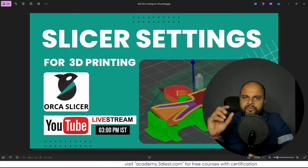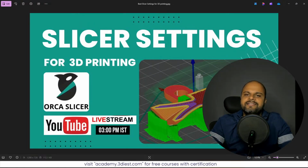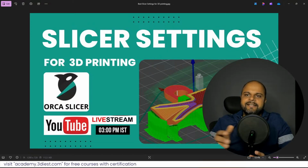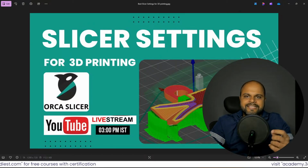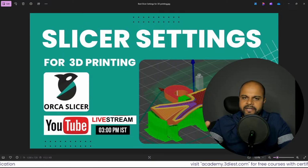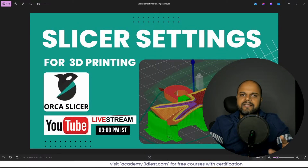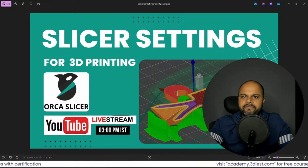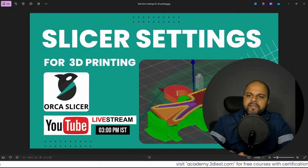Basically, whenever you create a solid model inside any 3D modeling software, you can export that solid model in an STL file format, right? You can use that STL file and 3D print it, right? But that is not possible, because 3D printers basically move based on the inputs that we are giving to their stepper motors, and those stepper motors are not able to interpret information from the STL files.